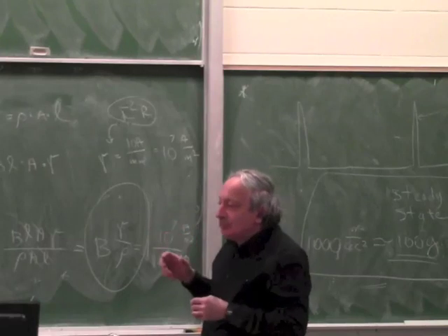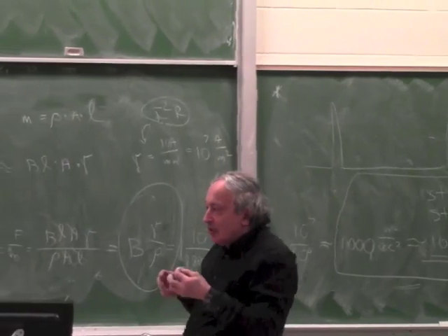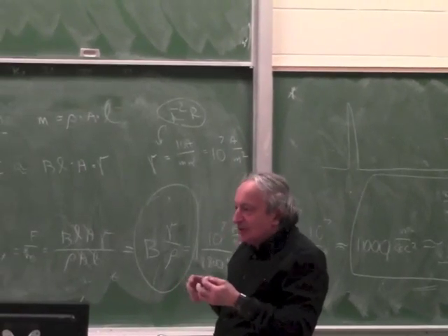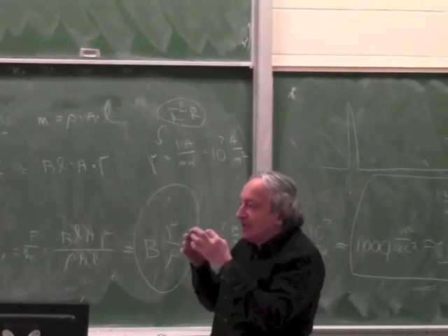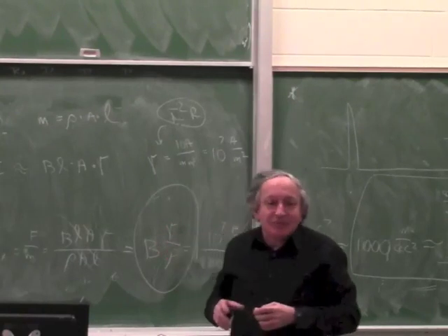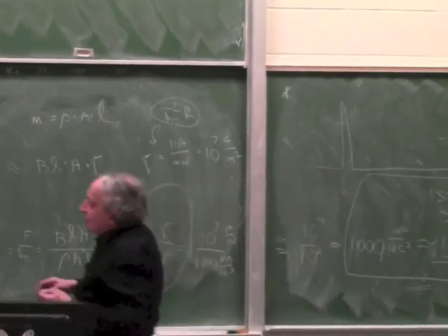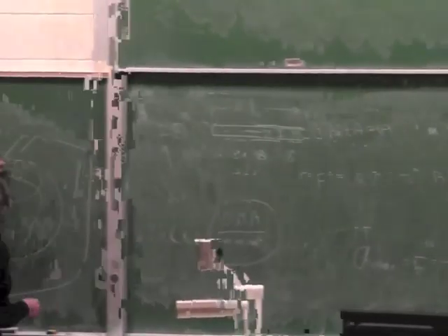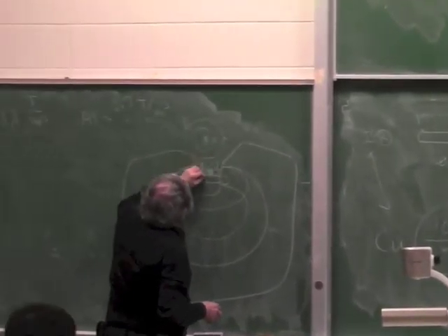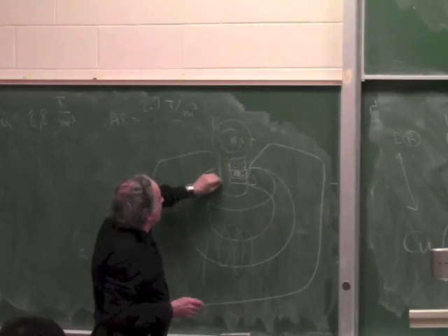If the wire is aluminum, it doesn't conduct as well as copper, so it gets hot. In order to keep the heat down, the aluminum wire has to be a bit bigger. That means the coil is a bit bigger, and the problem it causes is, if you want to fit the coil inside the magnet and you make the coil of aluminum, it's a bit bigger, you have to make the gap a bit bigger.